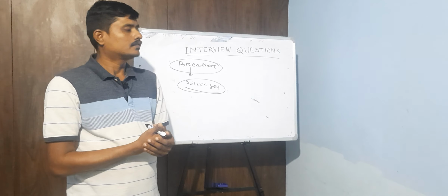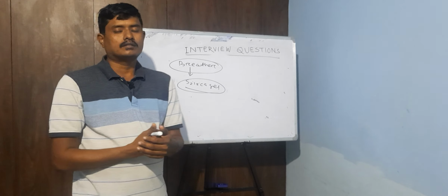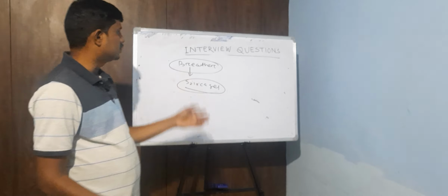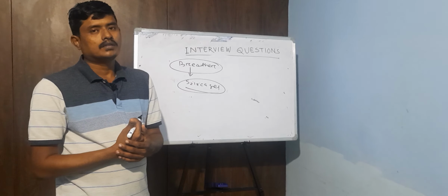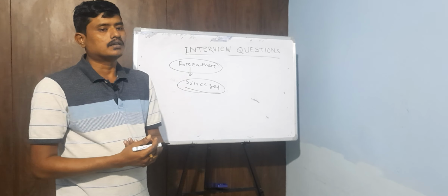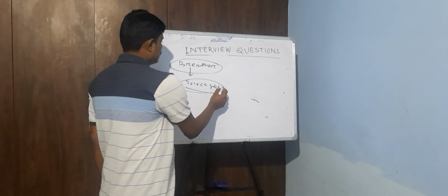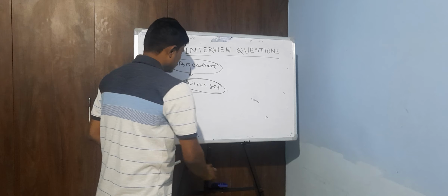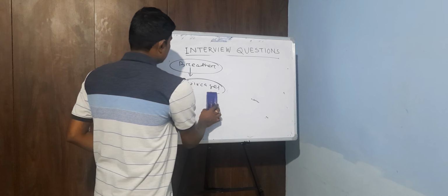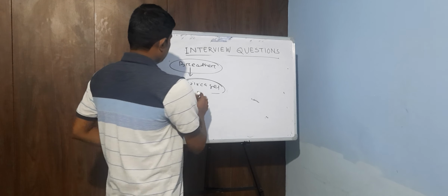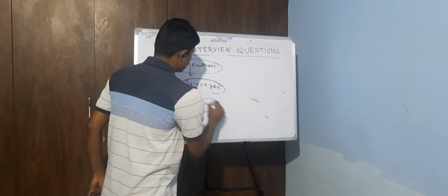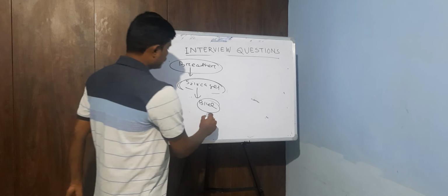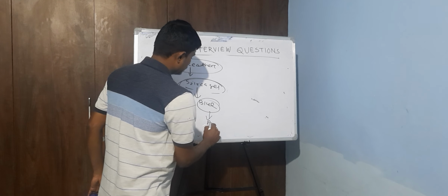When the fresh air enters into the breather, at that time it absorbs moisture from the air and allows dry air into the transformer. This is the basic function of silica gel. Its color is normally blue. So when it absorbs moisture, it becomes pink.